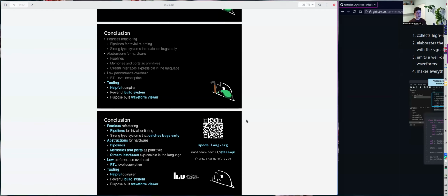It just essentially, while compiling, runs the synthesis tool, checks the critical path, and inserts registers on the critical path until you meet timing. So Pipeline C does it automatically. In Spade, it's more like you can more easily put more or fewer registers in there. If you have retiming on, you can put those at the end. If you don't have retiming on, you have to put them where you want them. Sure, this is still a huge improvement.